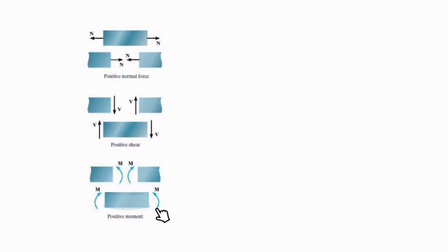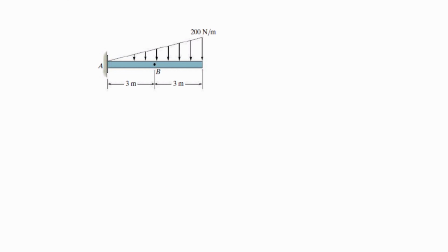As you can see, these moments are making this beam a concave shape, and we name these positive. As long as you have a picture like this one and you are on the right side, this is positive. And when you cut through a surface like this and you are on the left side, this is positive. We need to keep these things in mind and use these standard positive forces and moments for solving the equations.